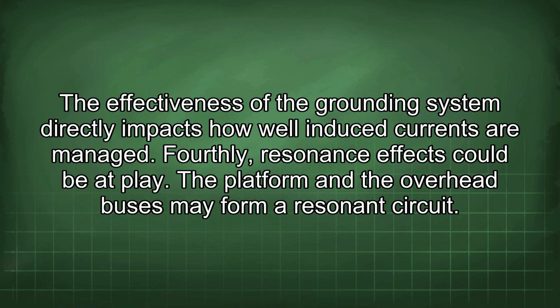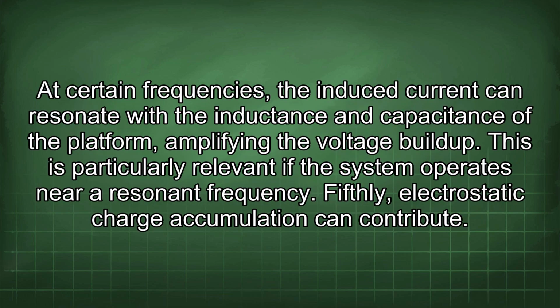Fourthly, resonance effects could be at play. The platform and the overhead buses may form a resonance circuit. At certain frequencies, the induced current can resonate with the inductance and capacitance of the platform, amplifying the voltage buildup. This is particularly relevant if the system operates near a resonant frequency.